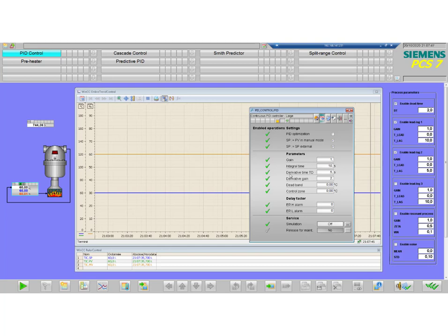And what works very often is to take as derivative time constant the secondary time constant, and in this case this is 5 seconds. Remember that this derivative gain is this 1 over alpha, and if you set derivative gain or 1 over alpha to 2, this means that the derivative kick will be 2 times the proportional kick, right?